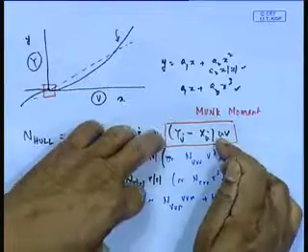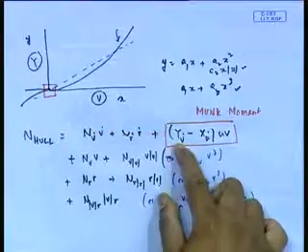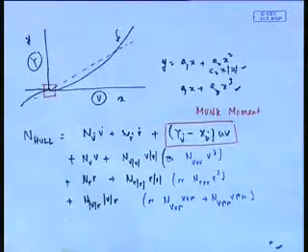So there you can neglect it, but in marine structures this becomes extremely important, because Y v dot is almost like a mass. Y v dot is proportional to the mass of the vessel. For a 20,000 ton vessel, it will be around 20,000 ton into u v. You can imagine the nature of the force.